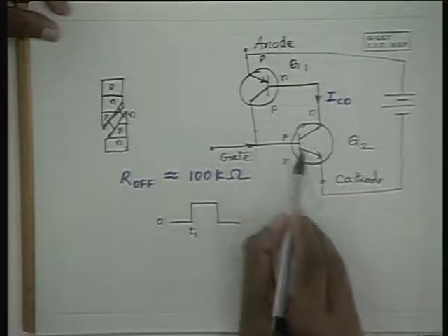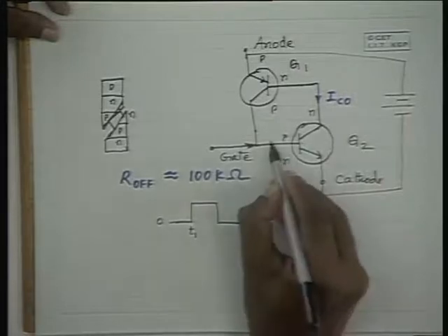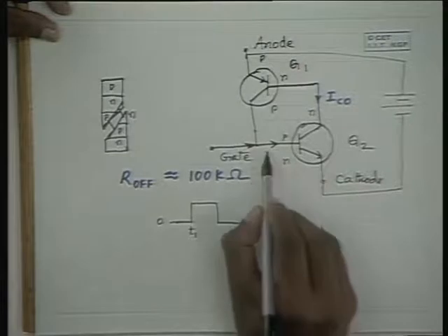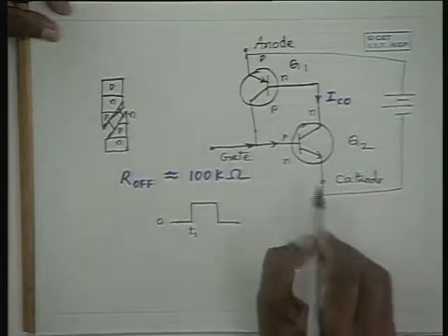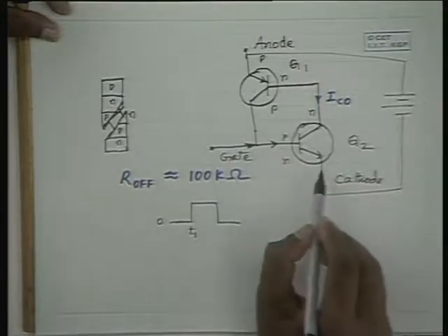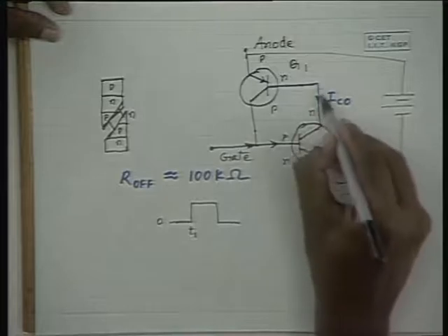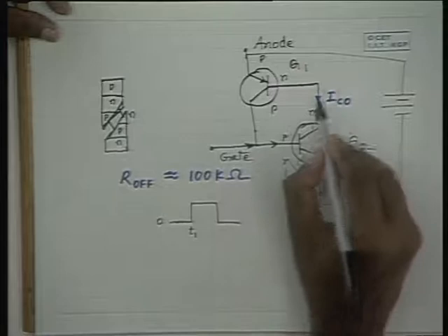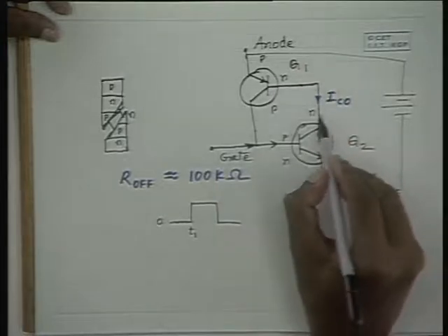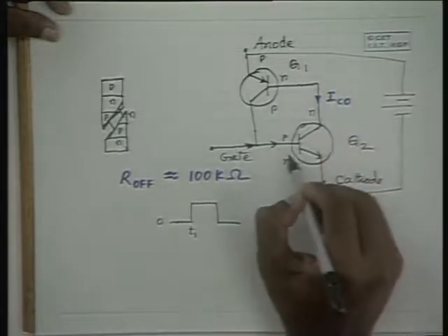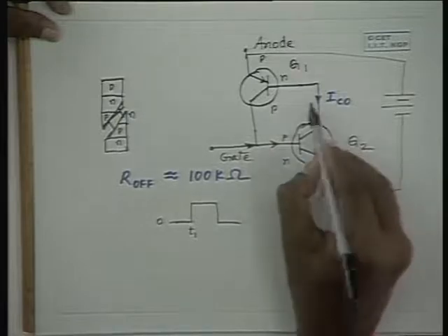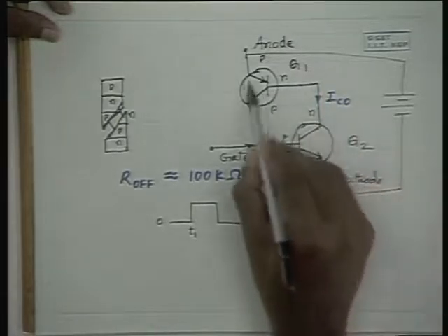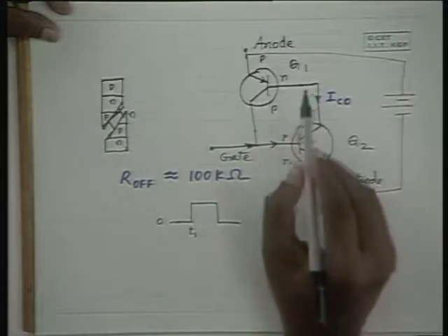Now in that situation, base current flows into this transistor Q2, this IB2 flows, and this current results in a collector current. So beta 2 times this IB2 would be the collector current, which is definitely much larger than this IB2, and this current contributes to the base current now for this transistor Q1.